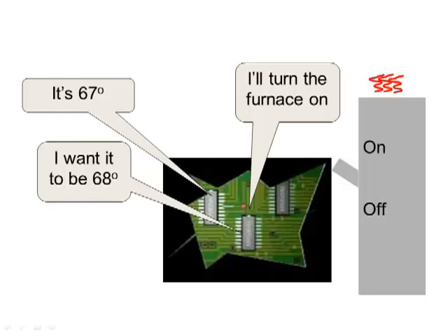So if you get home to a cold house and you turn the thermostat way up to 85, hoping that it'll get to 72 that much faster, it won't. Okay, back to the point. The thermostat checks the temperature, compares it to a preset temperature, and decides whether to turn the furnace on or off. And it just continually repeats that procedure.